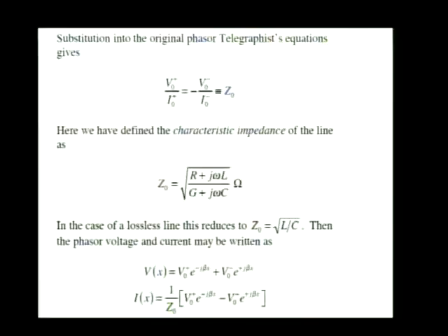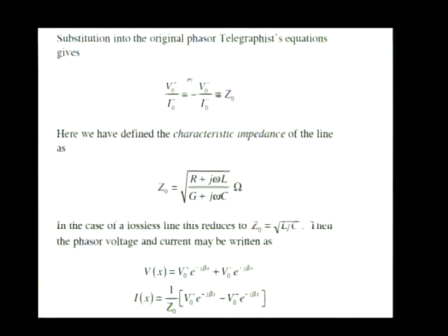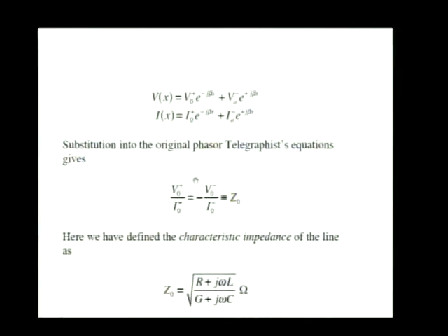in that equation. So these two terms disappear. Then you get just j omega L divided by j omega C under the square root sign. But the j omegas cancel out. So you really have just L over C under the square root sign. And there it is, the very simple form that the characteristic impedance takes for the lossless line. Now, the characteristic impedance of the transmission line is a very, very important quantity. However, it's also important to make sure that you interpret that quantity correctly.